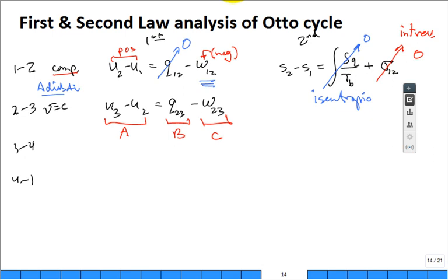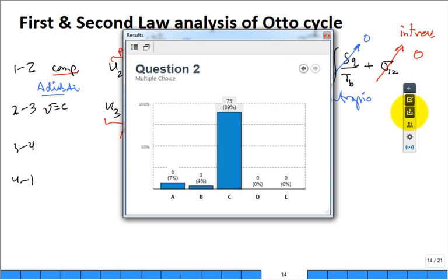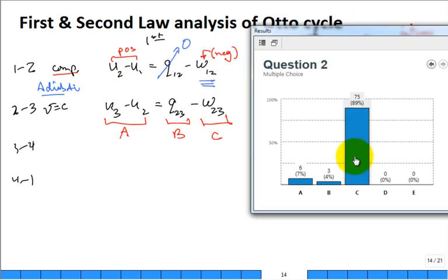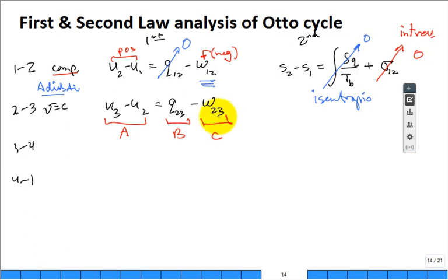All right, let's take a look. Absolutely right. Why is that work 0? It's a constant volume process. The pressure is going to go up, but what's the volume do? Doesn't change. The integral P dV is 0. Hence, this term is 0 for constant volume.